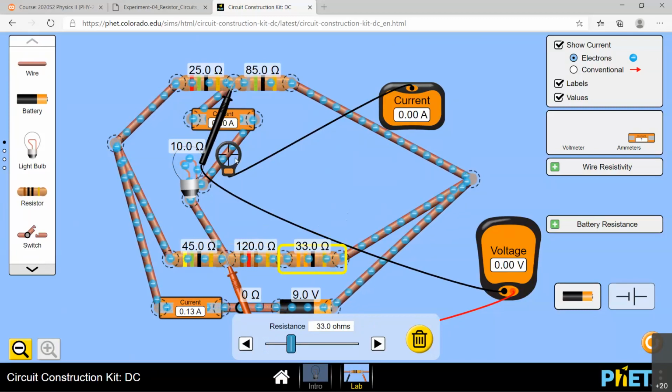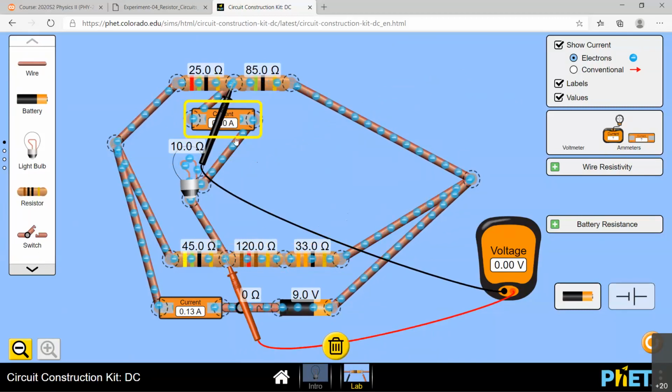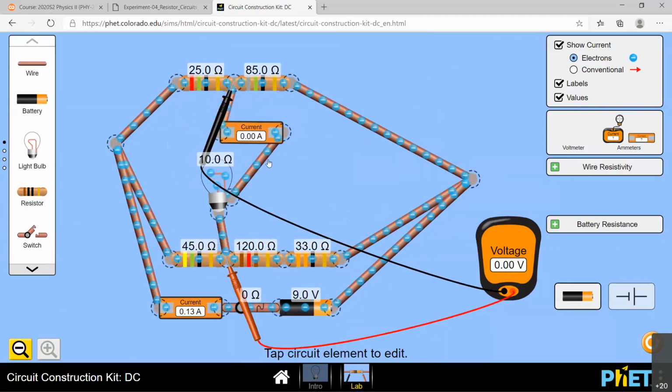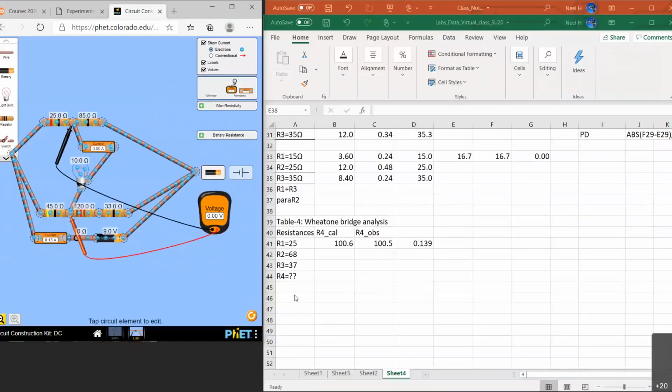Okay, good. Now that circuit you have to work around. There's a little bit of work to do there because not directly putting everything together, it's not directly working. Make sure all of this is visible before you take a picture. It's not the current 0 point we are interested in, because the ammeter seems to be not sensitive enough. You have to have the voltmeter across those two. Then take a picture, then complete the second line right here.